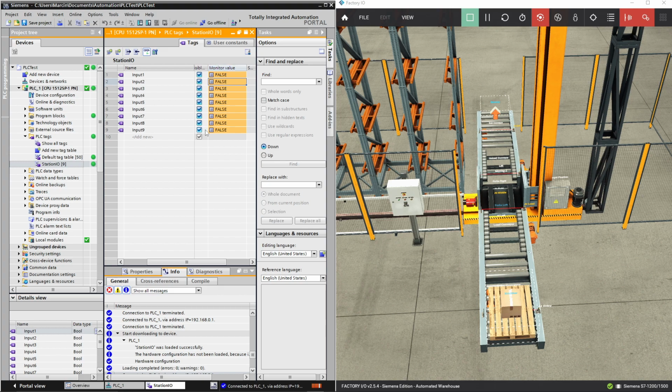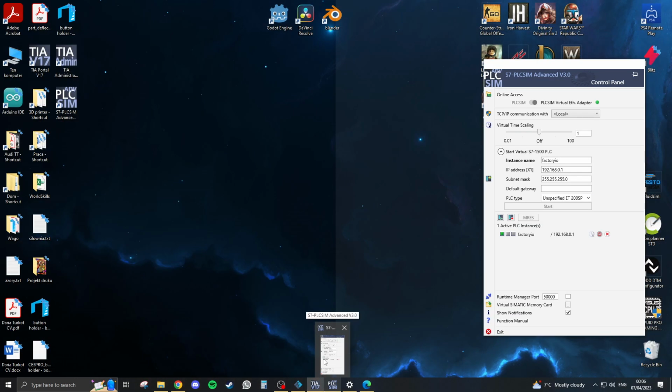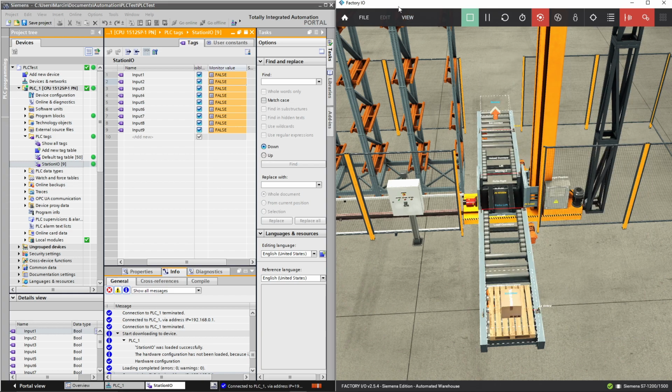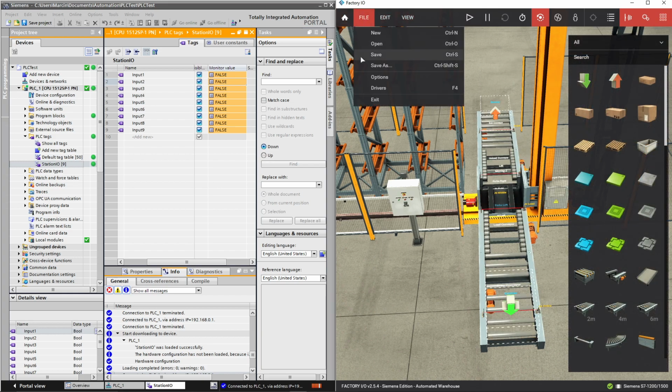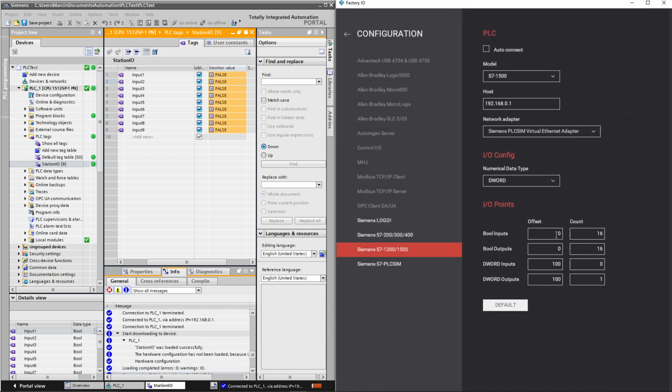There you go. Received from the actual physical inputs because there's nothing wired to this simulated PLC that acts like a real PLC in here. So it doesn't have anything on the physical signals. That's why when assigning my driver, I should actually not put it on the same byte as the real signals.